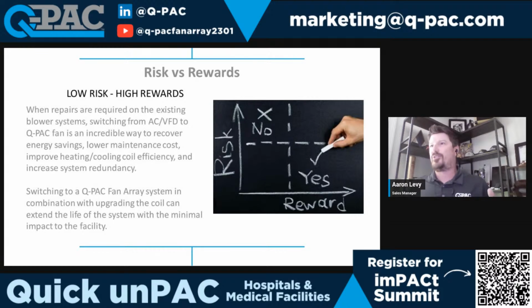So I see a question really quickly. It's over here in my peripheral about MTBFs. One of the big questions people ask about EC fans is about their life hours. The average, what we call the L10 or 10% field failure rate, is somewhere between 50 and 80,000 hours.